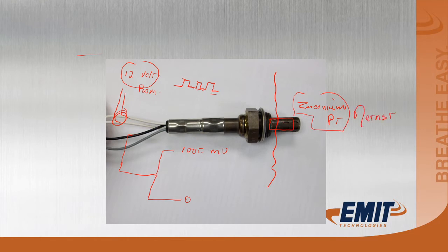Together, that cell in there is called a Nernst cell, N-E-R-N-S-T. Basically, we have current coming out. Just like when the catalyst was working and we have the electron discharge, the more raw fuel or unburned hydrocarbons we have going across there, the more current is coming off of here. Typically the most you could ever develop is 1 volt or 1,000 millivolts. On a typical rich burn engine, we're going to be running somewhere between 700 and 800, so let's imagine 750 millivolts is our target value.